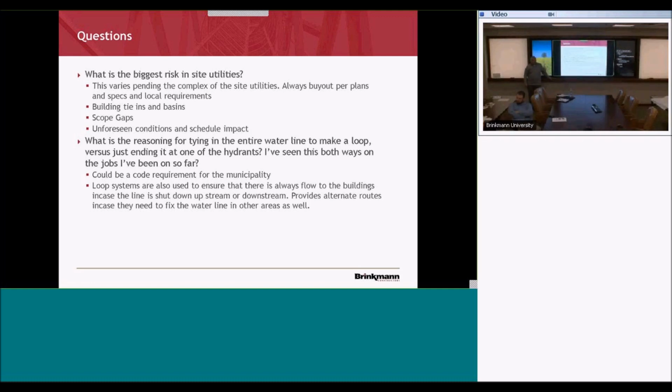whenever you're doing your site electric or your gas company comes, sometimes they don't have their civil plan, and you would think that the gas company that digs all day, every day would know how to read one. They don't necessarily. They just go 30 inches in the ground or whatever. So make sure that they're doing it per the plan and they're going deep enough, in case you have to dig some out. We ran into an issue with a cleat. The guy didn't even know how to use a laser that was running the job.